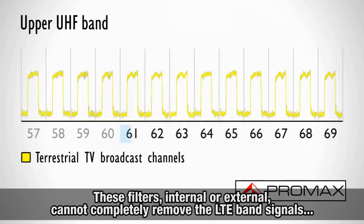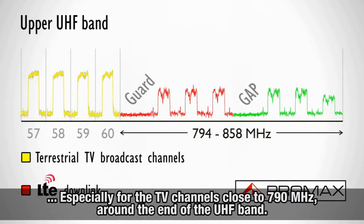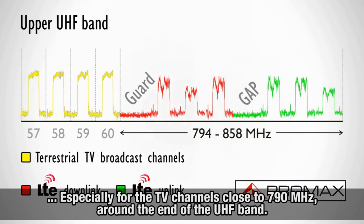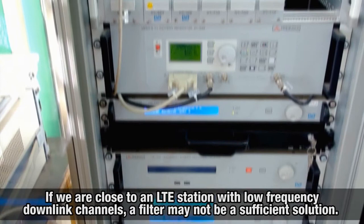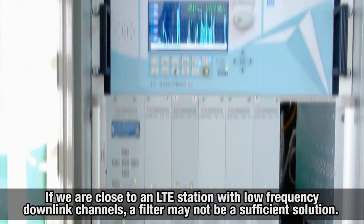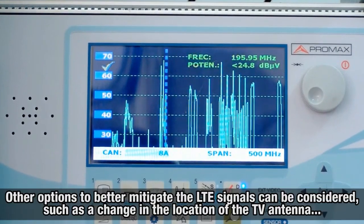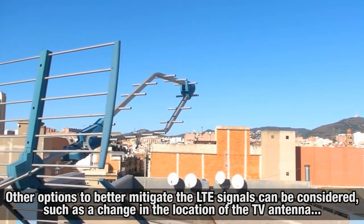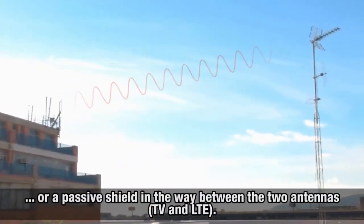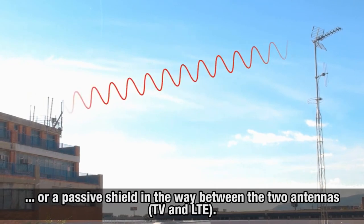These filters, internal or external, cannot completely remove the LTE band signals, especially for the TV channels close to 790 MHz, around the end of the UHF band. If you are close to an LTE station with low-frequency downlink channels, a filter may not be a sufficient solution. Other options to better mitigate the LTE signals can be considered, such as a change in the location of the TV antenna or a passive shield in the way between the two antennas, the TV antenna and the LTE antenna.